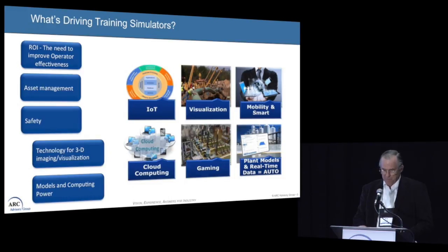Just to give an example, you could spend a great deal of time modeling one control valve. Control valves open and close at different rates. They have a certain installed characteristic, quick opening, butterfly, type of characteristics. They have stiction and hysteresis. And those characteristics change from day to day. They change from operating conditions. They could have flashing across control valves with cavitation and noise. Are you going to simulate all that detail in your operator training simulator? I hope not.